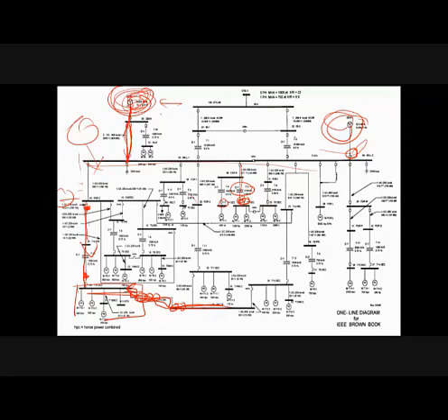We have a few generators disconnected because of faults on the transmission line. Let's say this fault occurs, and the fault is not cleared. This generator will become overloaded. Maybe if one generator is broken, it's still okay. Other generators can support.